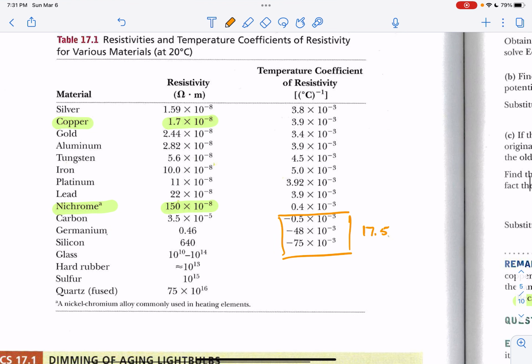So if you look at this chart, you can see that by far and away most of our wires are copper. Back in the 70s, when copper was really, really expensive, a lot of houses used aluminum wire. And I've lived in a house with aluminum wire, and every time I wanted to put in a new switch or an extra outlet or wire something in another place, I would use copper wire. But if you had a copper aluminum junction, it would generate heat, and that's not good.